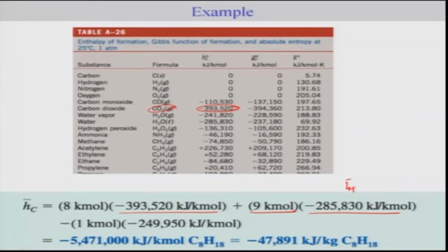hf for water, particularly the liquid state. So this comes from here. This would be from here. Okay, and this comes to here. Okay, and then you have this in the reactant for C8H18, the liquid octane, and you can get it from the table as well. Okay, from here we can do the simple calculation which will yield this heat of combustion per unit mole. You can convert this to per kg as well. Okay. So this is a simple exercise making use of the table and the stoichiometric equation analysis of the reaction.